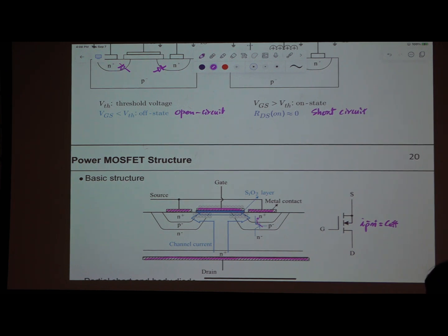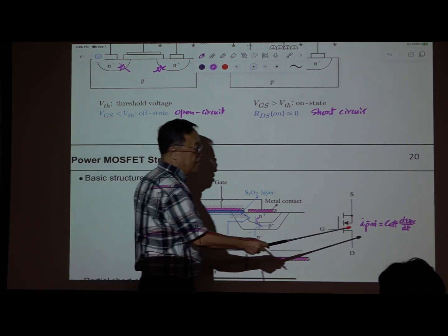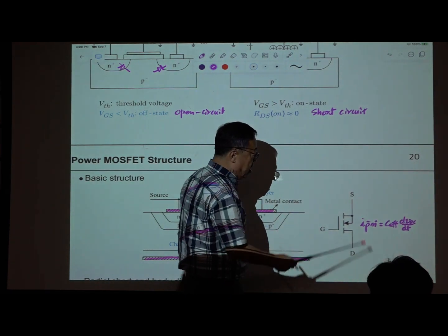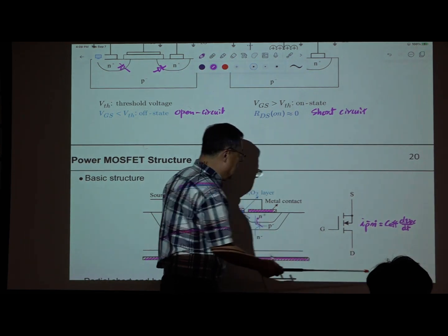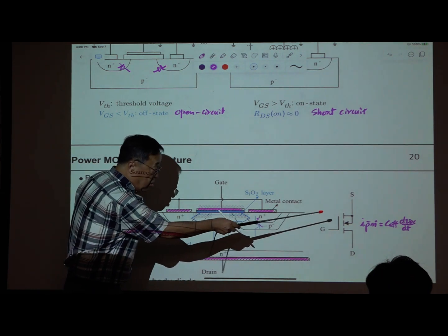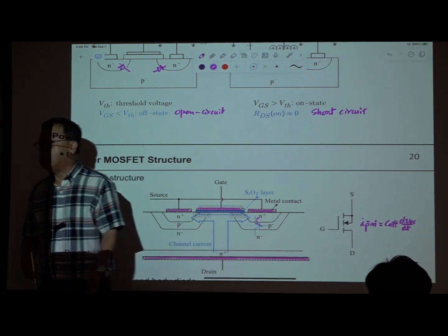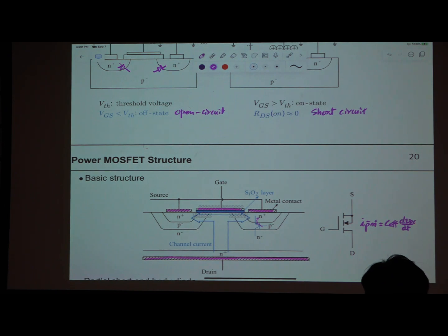and this is the basic equation, dVDS divided by dt, okay? So for high-speed switching, this will be very large, all right? For a fast switching device, this time derivative of this voltage will be large. Then that current will be large. That current will turn on, and this diode will turn on. Then this device is not a MOSFET anymore. It's some strange device that should be avoided. Otherwise, it's not working properly. It's not working as intended.